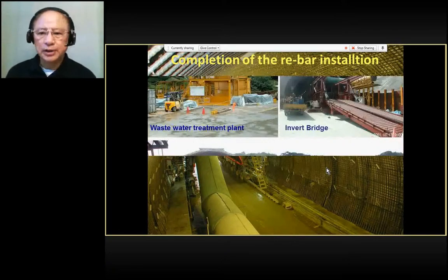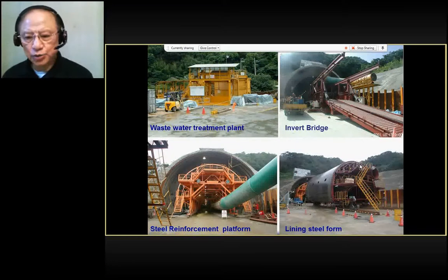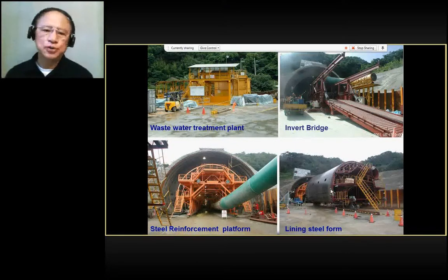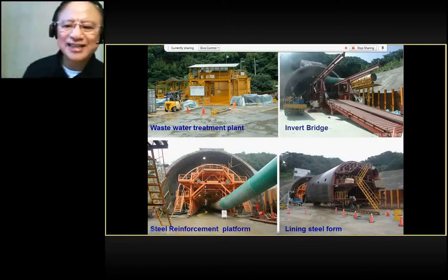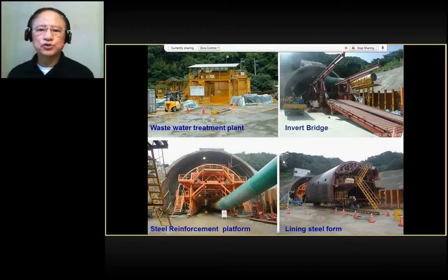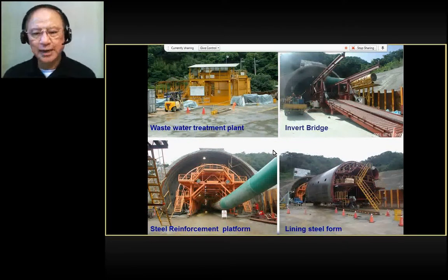Okay, so this is the inner mold which I talked about. This will move in after the rebar and membrane are in place, and you start grouting from all these holes. Okay, so that is how you construct the tunnel with lining and waterproof membrane.